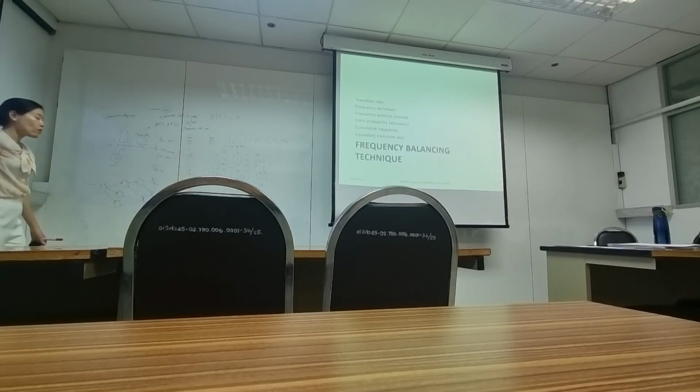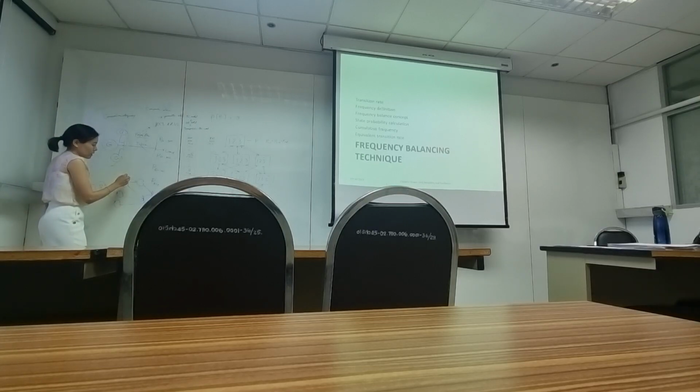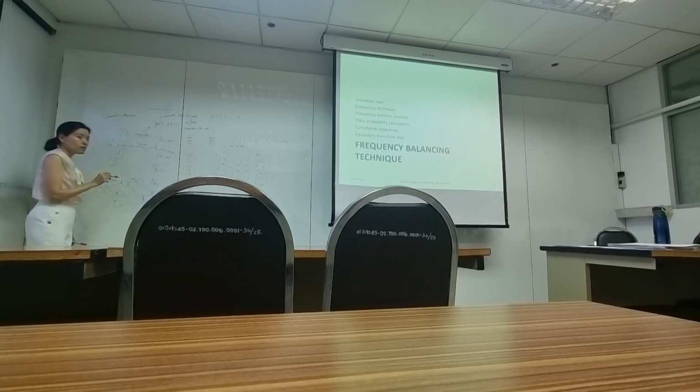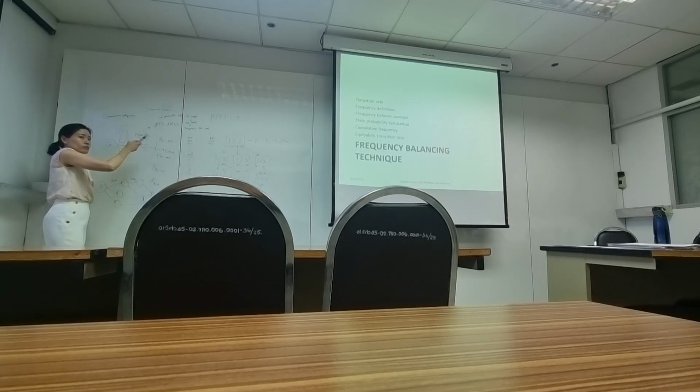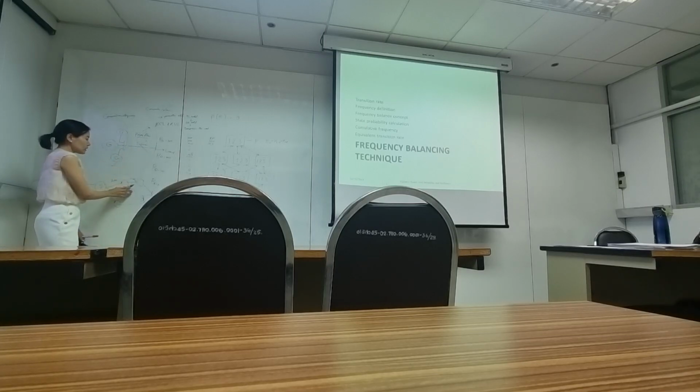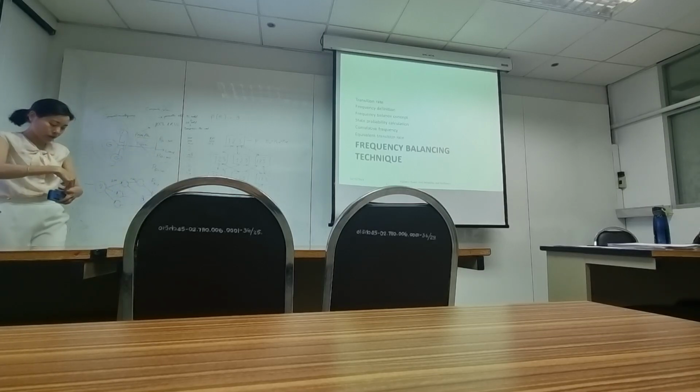So in the network flow model, you only look at the capacity of the transmission line, say 200 megawatts, 100 megawatts, but you don't look at Kirchhoff's voltage law, meaning the congestions, how the electricity actually flows. So these are the different models.